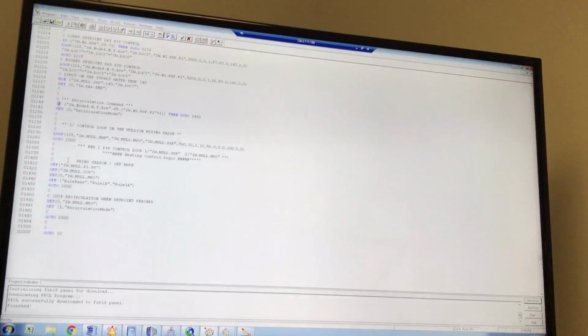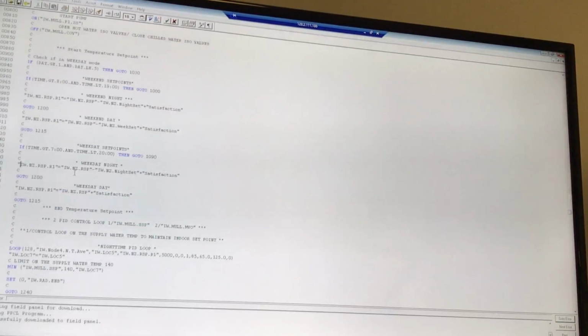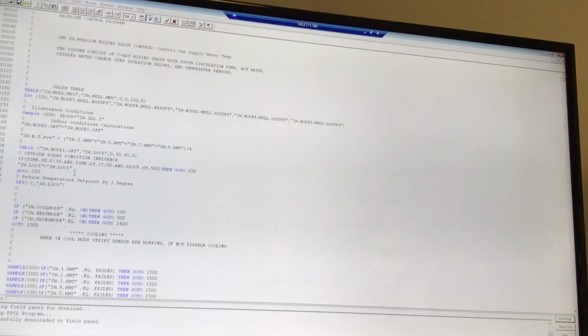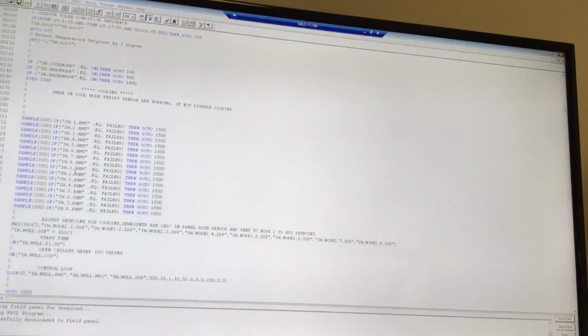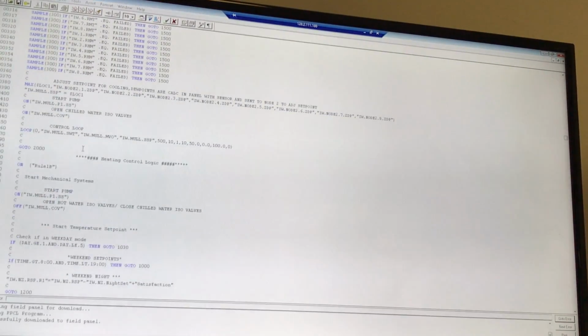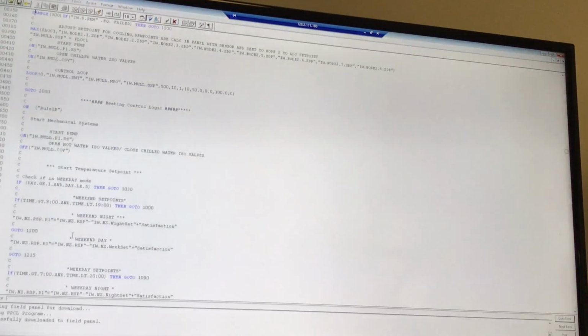What's our startup time? Is it a variable startup time, or do we always start at the same time? Right now I think it's always rule 7, at 7 a.m. And it's warm by 8, or 8:30, even on the coldest days, almost. But it's something somebody who wants to work on advanced optimization can work on. And our shutdown time? 7 p.m.